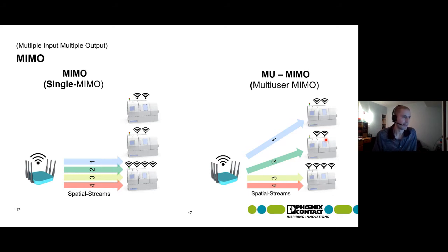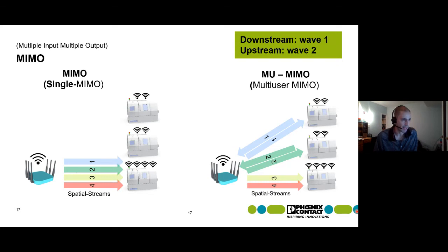In the first release of Wi-Fi 6, for downstream communication from the access point to the stations, you're going to have the ability to use this multi-user MIMO function to, again, make the use of the spectrum more efficient. Like AC and Wi-Fi 5, there are 2 releases. The plan is to have a second wave of Wi-Fi 6 releases that will provide upstream multi-user MIMO as well. That way the stations on the remote side, if they need to push updates, can split up those streams and communicate simultaneously.